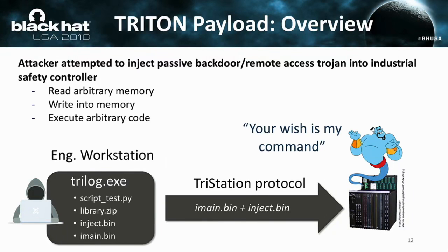Even though the TRITON implant lives entirely in the memory, because safety instrumented systems, like safety controls, are typically never rebooted, the only persistence the attacker actually needed to achieve is to move it into the part of the firmware which will not be overwritten by the override of the control logic. We will go through the steps in the presentation, so I will not detail them right now.